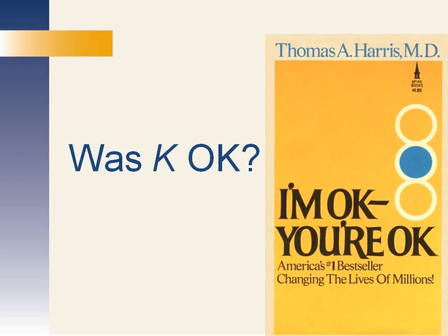Well, it's fair to say that K was used, but it was introduced not without compromise. It was true then, and it remains true today, that few, if any, of the assumptions that are behind those alignment charts are actually satisfied in real structures. In the end, we can say that K was accepted because it did something, and that was better than doing nothing.